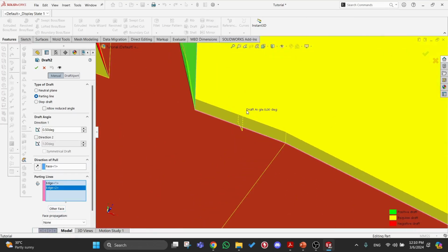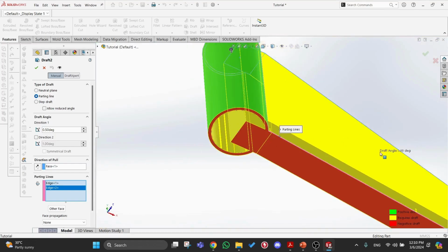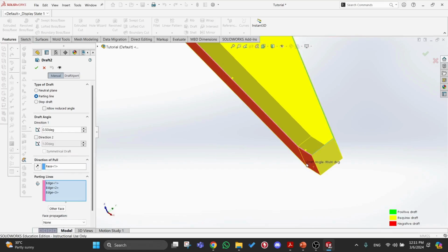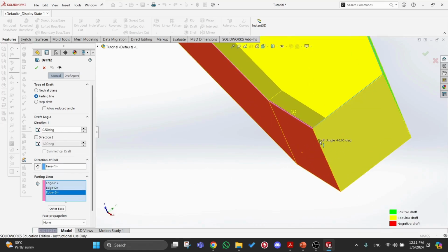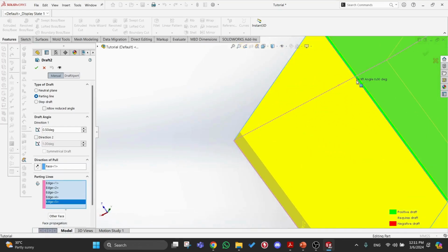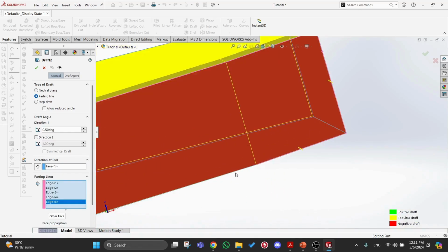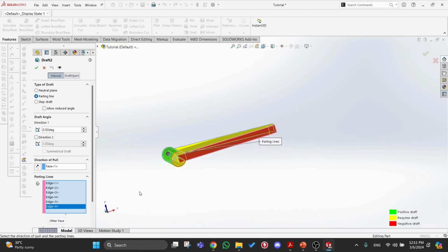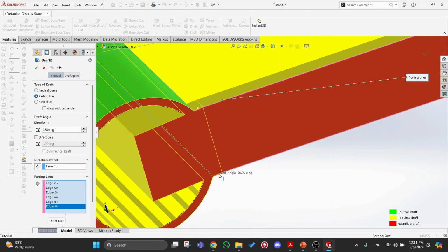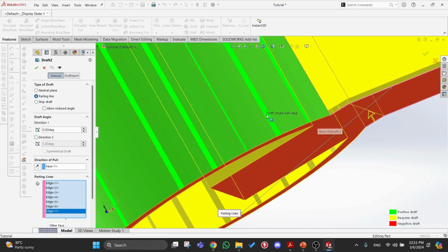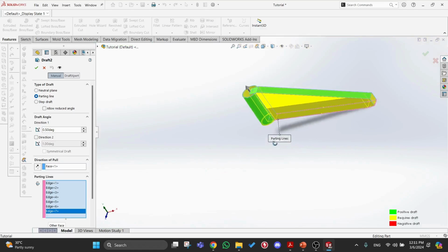So you want to click on all of this line so that it drafts inwards, and you can see that down here there is no draft at all. This is important. Remember, that's how you differentiate them. You can see here, draft outwards, inwards, and no draft, so it does not change your dimension. Very important. This is fine down here because it starts down here and your draft inwards starts here anyway, so it is fine then.